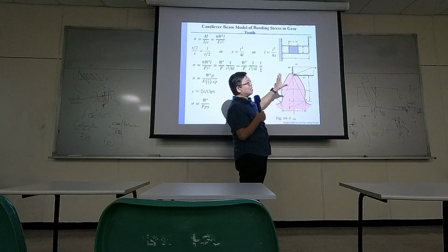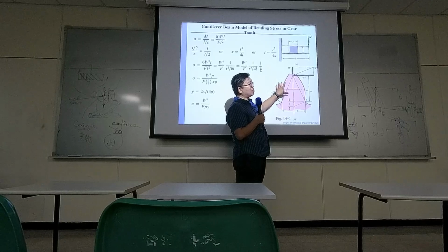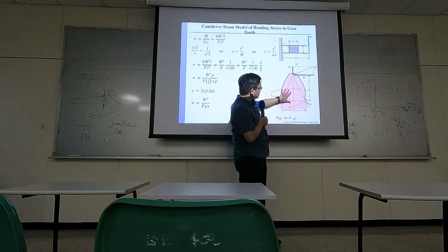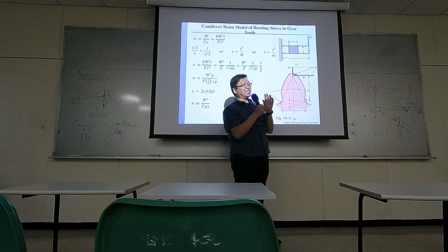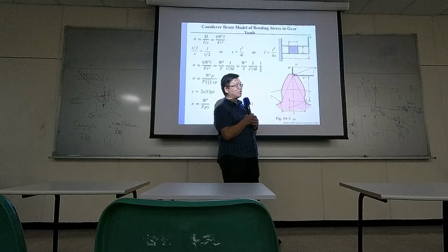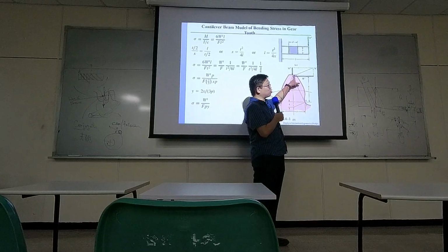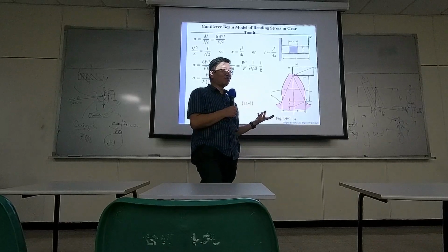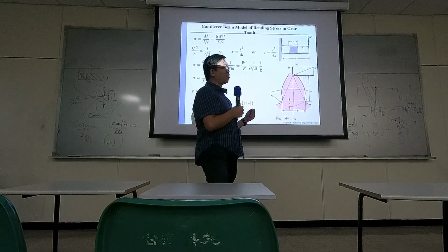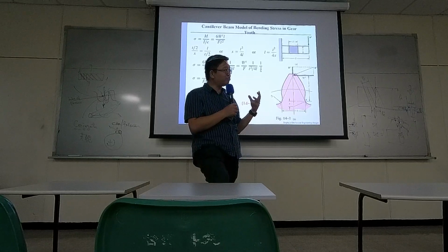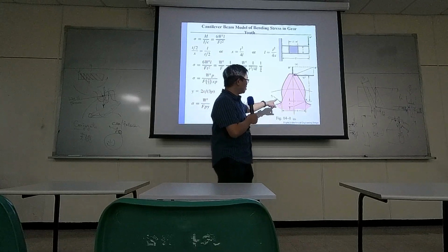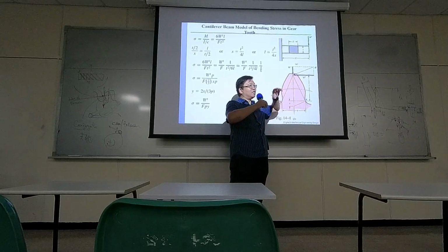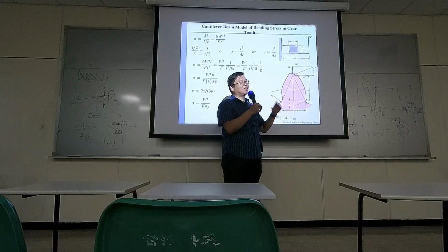Which one may damage the teeth the most? Actually, it is the transverse one, because the transverse force is a force that tries to bend the tooth. So if the transverse force is too large, the tooth can break. So if you 3D print a gear, the most probable failure you can have in a 3D printed gear would be a crack at the root, because the transverse force is bending the tooth.